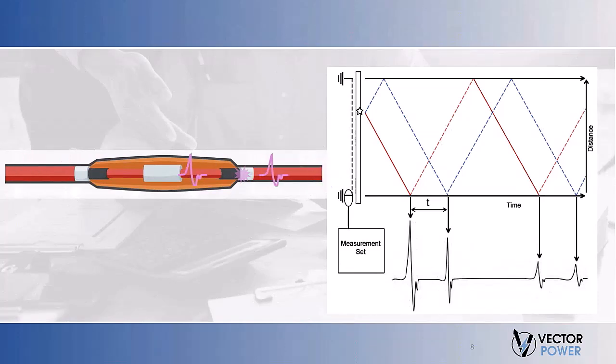Discharge sources can be found at various points within a cable system. However, there are limitations on the number of access points where a user can install a sensor to detect the partial discharge. When a PD event occurs, it generates an electromagnetic pulse that travels as waves through the shielded cable system, which functions as a waveguide.